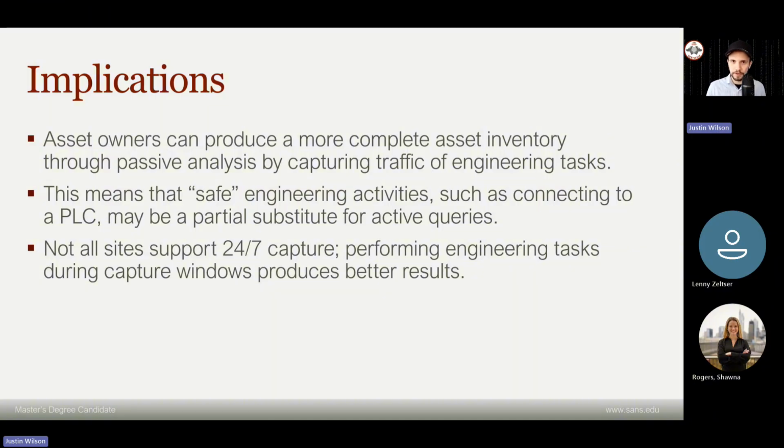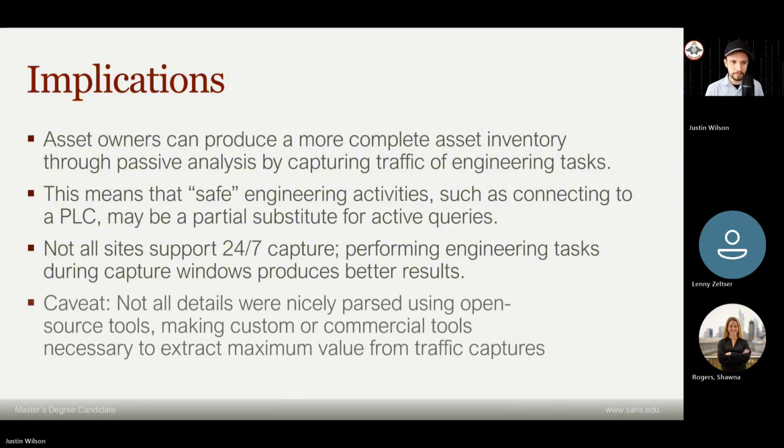But if you're going out there to take a packet capture for the purpose of building an asset inventory, you want to make sure that some engineering tasks are included in that capture. Connect to the PLC at a minimum if you can, because that's going to produce much richer asset details, and you'll have a much better asset inventory by including that engineering traffic.